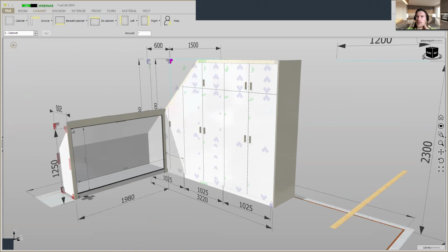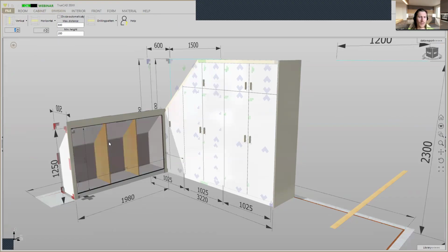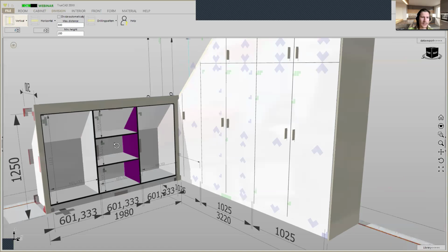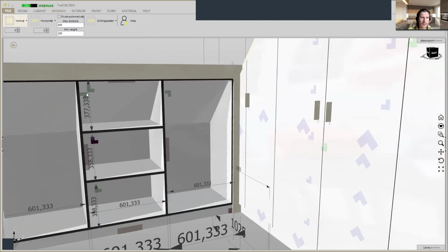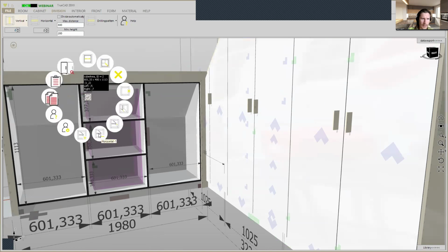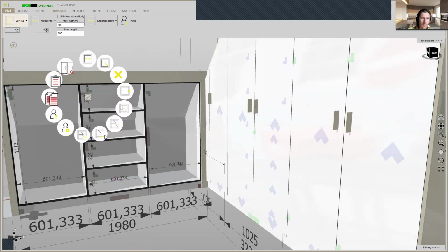Okay, now let's finish our project. We have set up the trims, and we go to the division, and we do want to have here two verticals, and in the middle we want to have one horizontal. If you do have accidentally two like this, you can also go here on the smart click for the whole area and click here plus or minus.